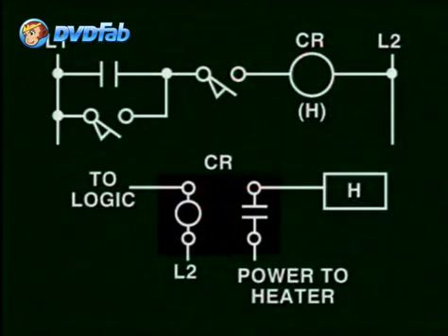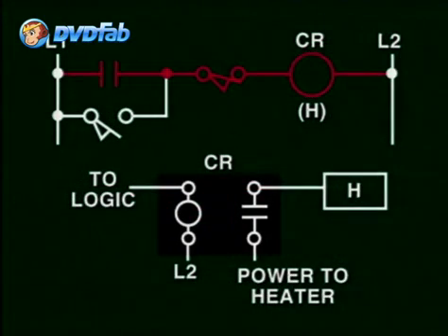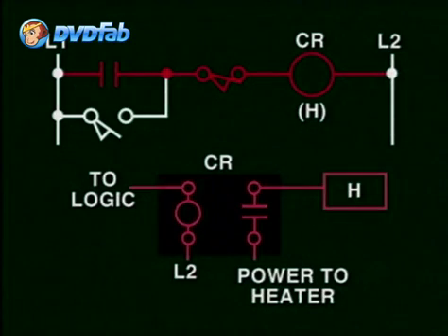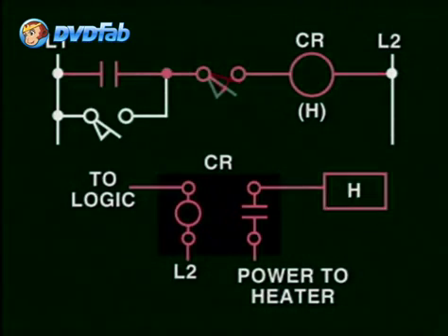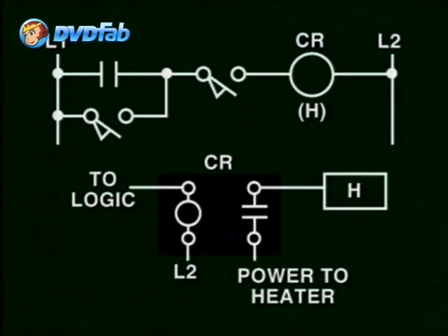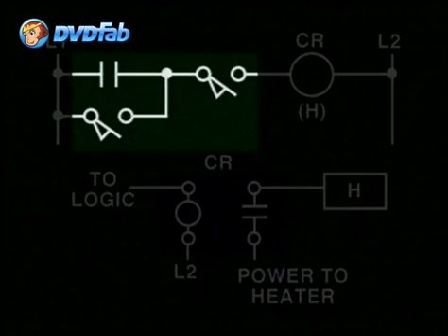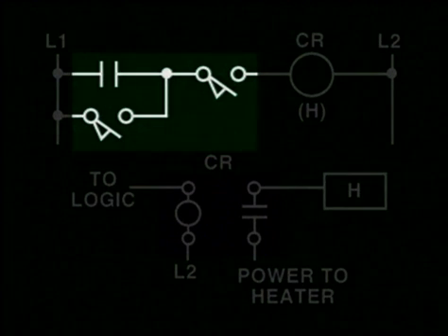In the case of a heating element, the heater control relay is the one which activates the heater to provide work, in this case, to raise the temperature. Regardless of whether the output control is direct or indirect, the loads are activated by the control circuit through the reading of input signals and the definition of its logic decisions.